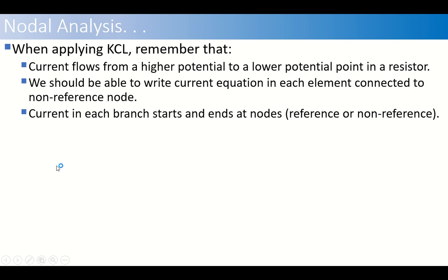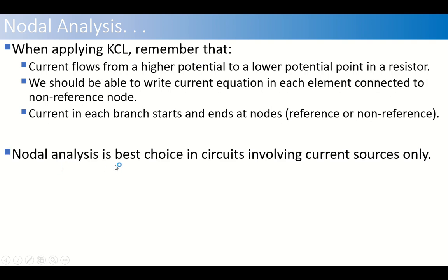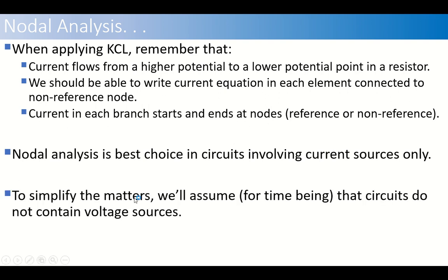This is again obvious. Nodal analysis is the best choice in circuits involving current sources only. We can generalize that if we have only current sources in the circuit, nodal analysis is the method that is particularly applicable.